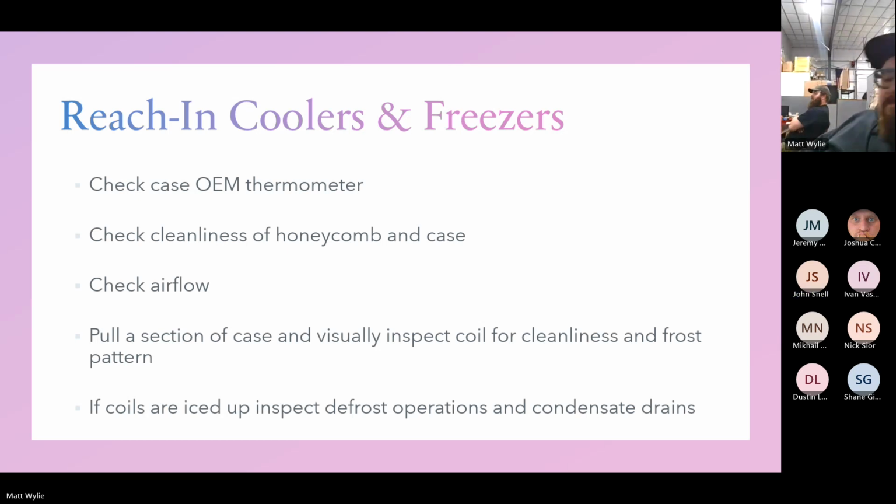Yes. I've noticed too, in some of my experience, the thicker, heavier, colder type ice shows up if you're flooding back or you have low superheat, if that coil is just saturated and can't evaporate that liquid.